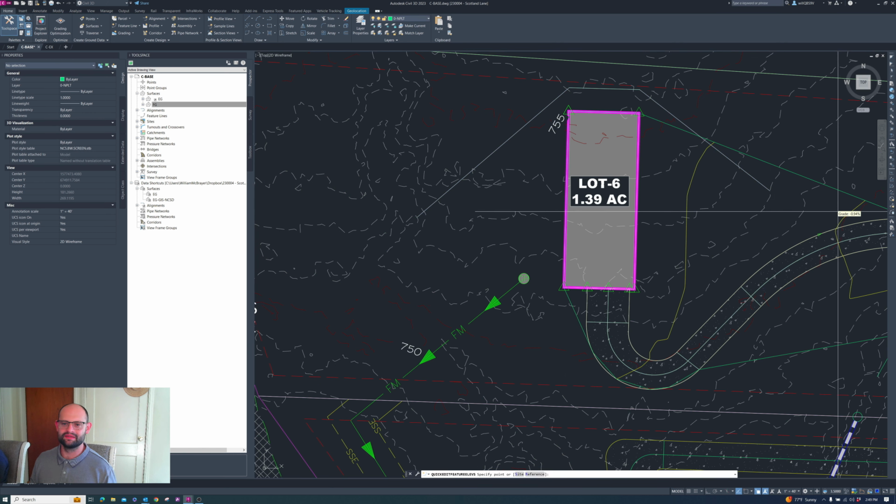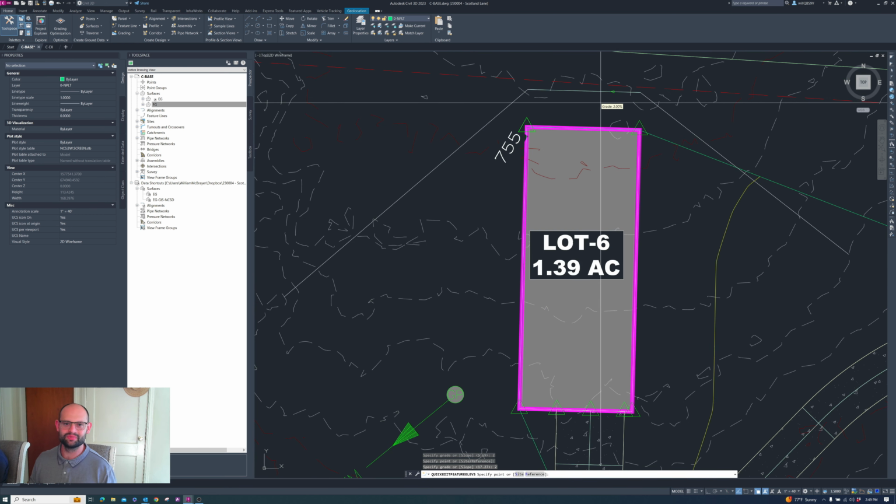Let's check the other end. 752, that might just work. Let's go up at 2%. Up 2%. We're at 753.705. Not quite going to work. We're 10 feet away from that slab here, so we need to be between half a foot to a foot lower. So let's just start at 752.75 there instead, and we'll work down at 2%, down at 2%.